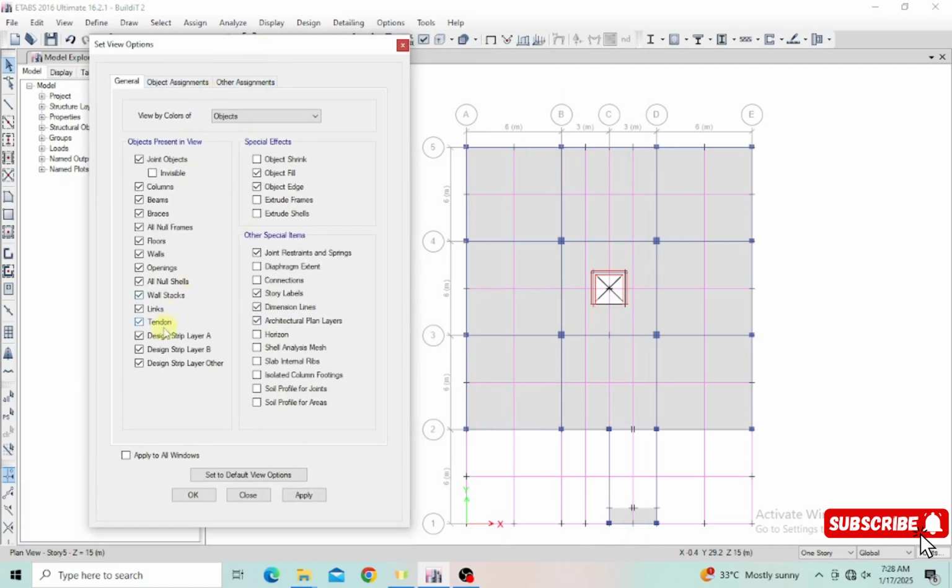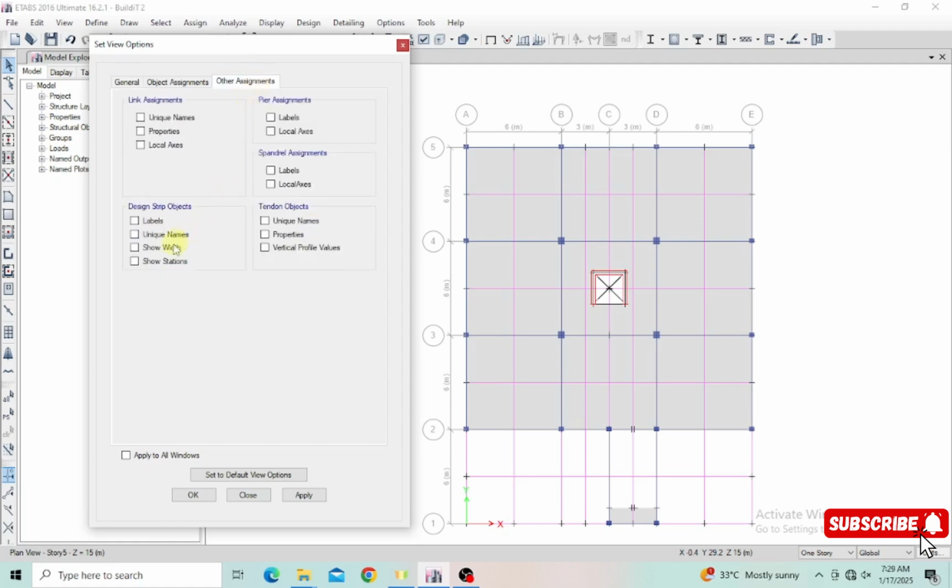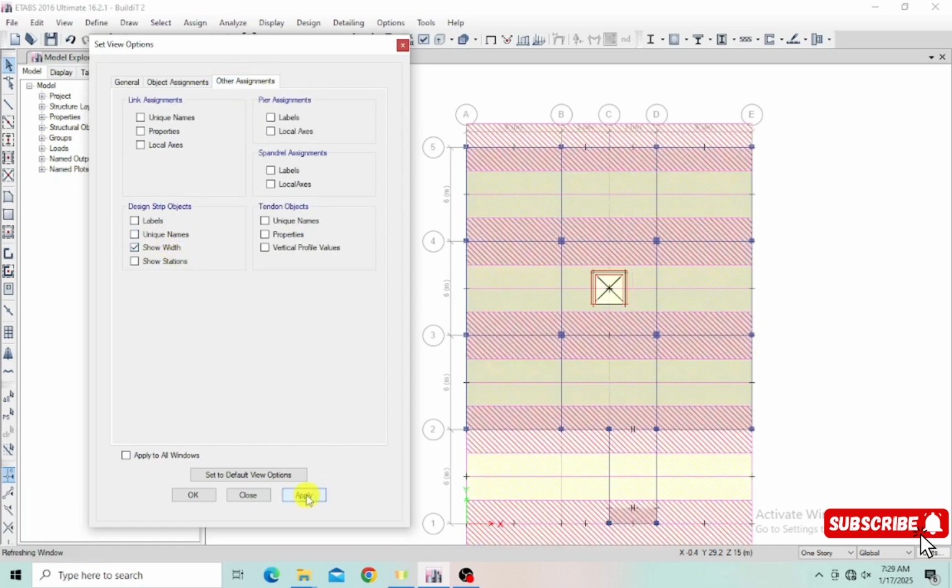Let's say you want to view only the strip layer A. So I'm going to uncheck the strip layer B, and I'll go to other assignments over here to show width. So the width of this strip, I'm going to just apply. So this is my strip layer A, and this is how the width is going to be. So with the shaded places here, this is the column strip layer along the column, and these are the middle strips over here. So this is the width here along this strip.